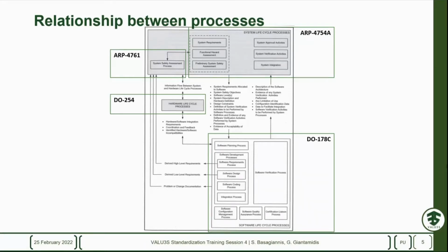For example, in integration testing, when we would like two different subsystems inside the aircraft to communicate with each other, it has to pass a series of checks, for example message integrity when you are using the AFDX protocol inside the aircraft. You have to be sure that the message being sent from one device to the other complies with the quality assurance of the message being delivered by the rest of the devices.